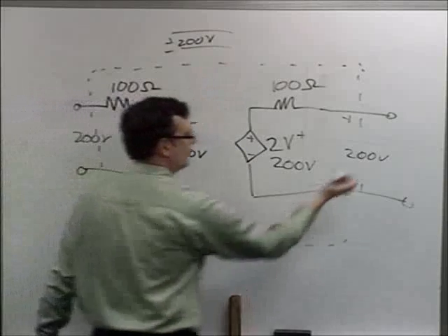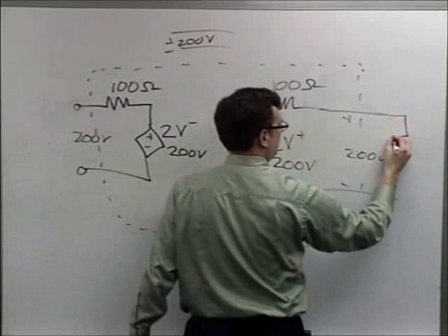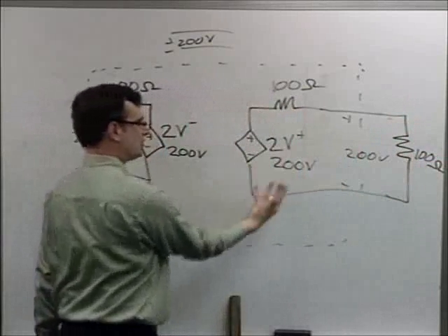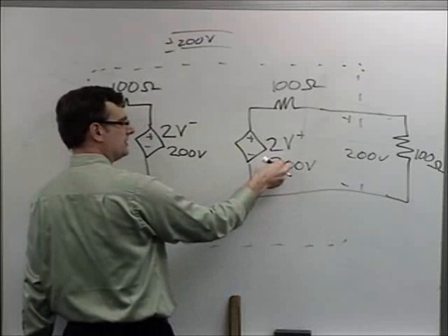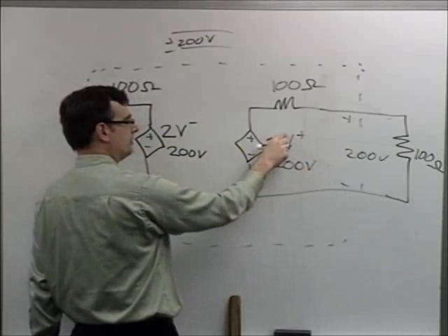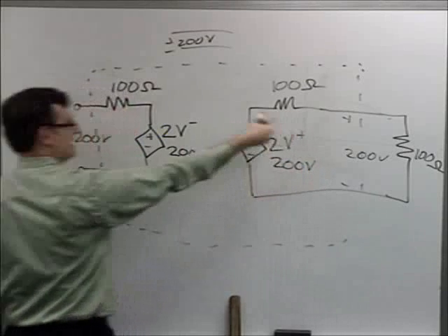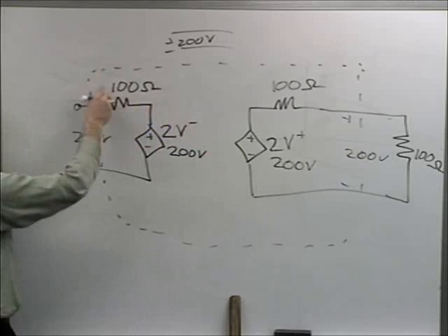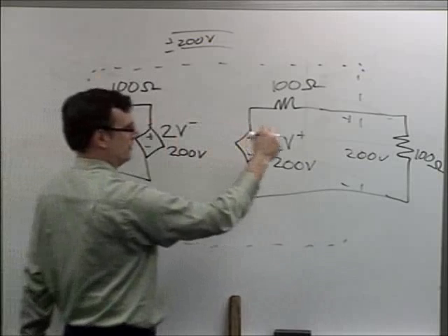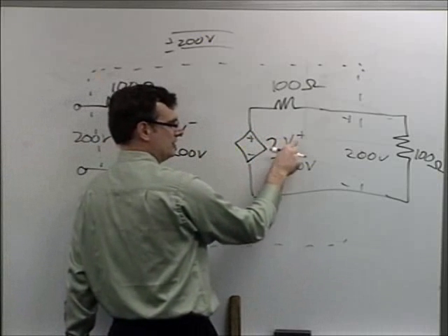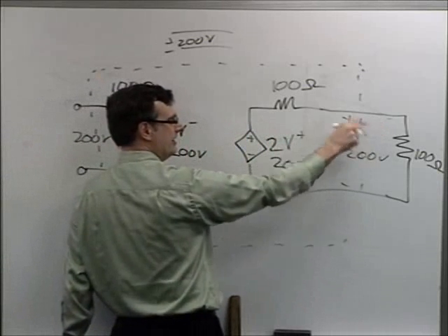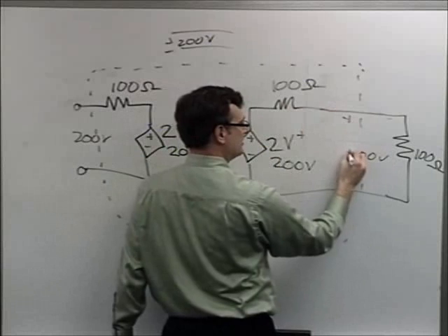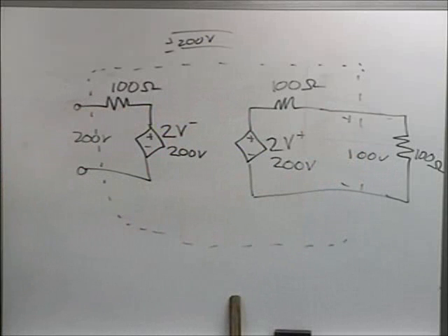Now here comes the 100 ohm finger. In this circuit diagram, now I've got 200 volts, which isn't going to change, because remember, the V plus that got put on this line has been traveling down there equivalently since one transit time at least, being reflected from this junction over here. So I still have 200 volts, still have 100 volts striking the end. Now I've got to divide it over 2 resistors. So that's why immediately as the finger touches, this immediately drops down to 100 volts.